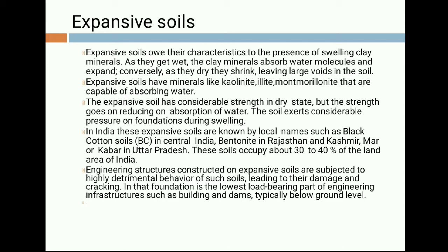This is very important. The black cotton soil in its natural state is having a considerable strength, but as the amount of water present in the soil fluctuates, that is, if the amount of water increases, it swells, and when the amount of water inside the soil decreases, it shrinks.